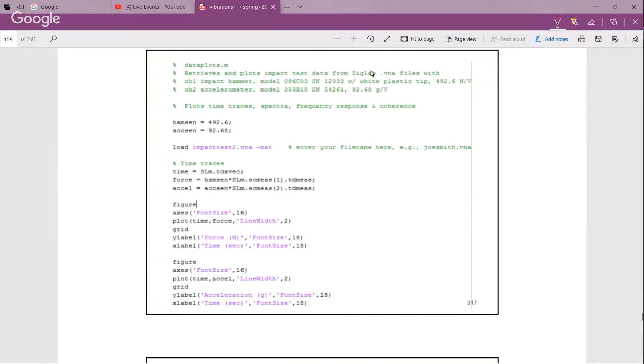I'm going to expect you to download it onto whatever computer you're using that has MATLAB or access to MATLAB. You pull up MATLAB and you type data plots. Is data plots going to come up, or is it going to say we don't know what you're talking about, or whatever error it gives you when it doesn't know? It's probably going to say we don't recognize it unless you set the path, unless you tell MATLAB, hey, check this folder here for stuff like M files that I'm going to use. You should set the path. I'll show you how to set the path. Should have done it. I don't know what you're doing in the 2 courses that we teach. You don't know how to set a path, but I'll show you.